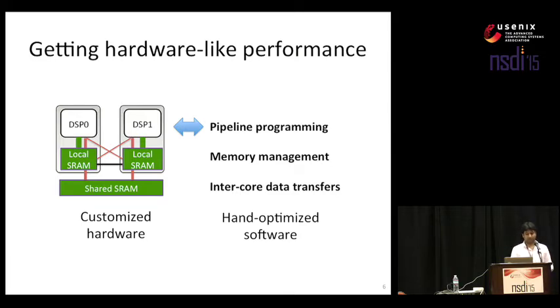Now, the other difference that we see from traditional architecture is that these platforms will typically expose very low-level interfaces to the memory architecture. As opposed to a typical general-purpose processor, which will have a rich cache hierarchy, these processors actually expose the SRAMs at L1 and L2 to the software itself. The programmers leverage this to carefully manage placement of data in the memories and therefore tune its effect on computational performance and the resulting latency, right?